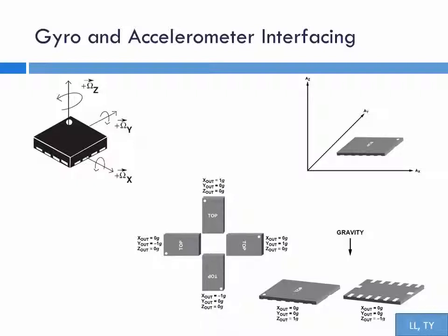On the right, we have the motion sensor ADXL345 used as the accelerometer. It measures the gravity vector of each axis. Note that a measurement reading is always opposite of the gravity. Take the upper view of the 4 position drawings, for example. Gravity is pointing straight downwards, with the y and z planes perpendicular to it. So y and z readings are always 0, whereas the x-axis, pointing exactly in the opposite direction of gravity, has a reading of 1g, not minus 1g.